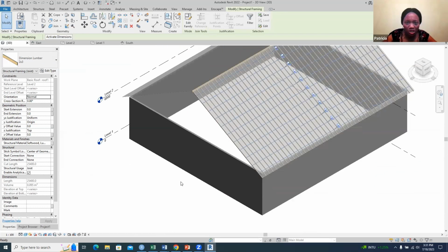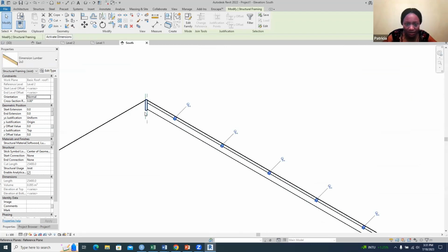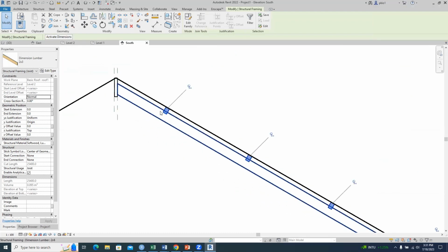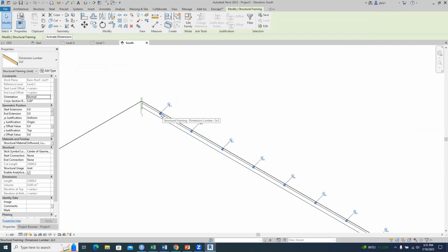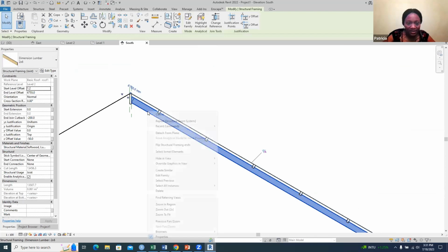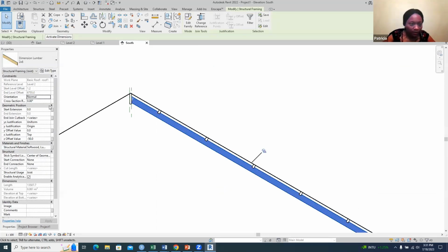So you see that it has changed the orientation, but still to check, is it at the right height? So is this the right height, or do we need to move? The rafter needs to come down a little bit also. Okay, we'll bring down the rafter and then we are fine. Okay, so select this and then all instances, and then we come to their Z. So let's make it minus 75 because now it has space for 50. So apply and then that's minus, fine.